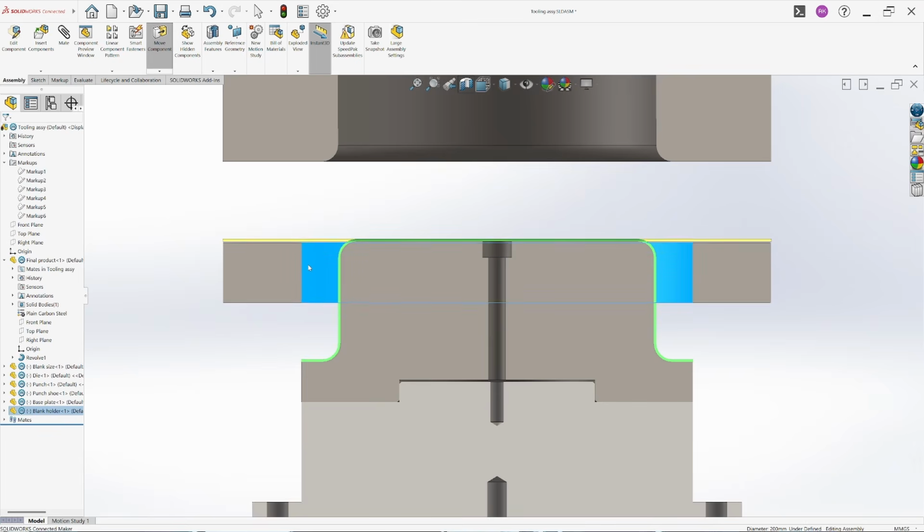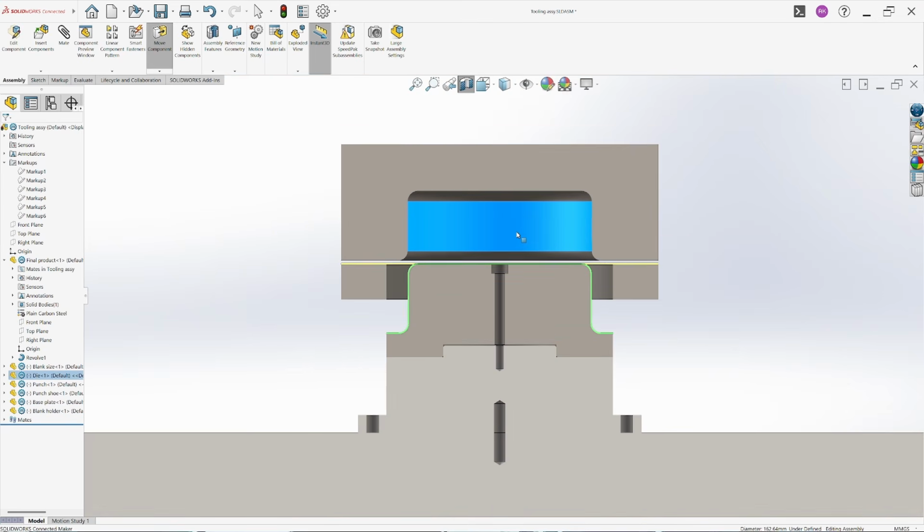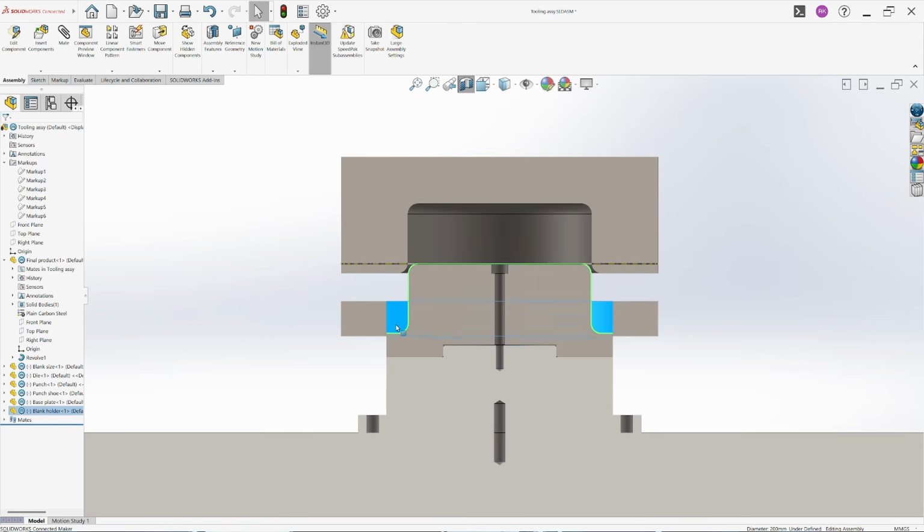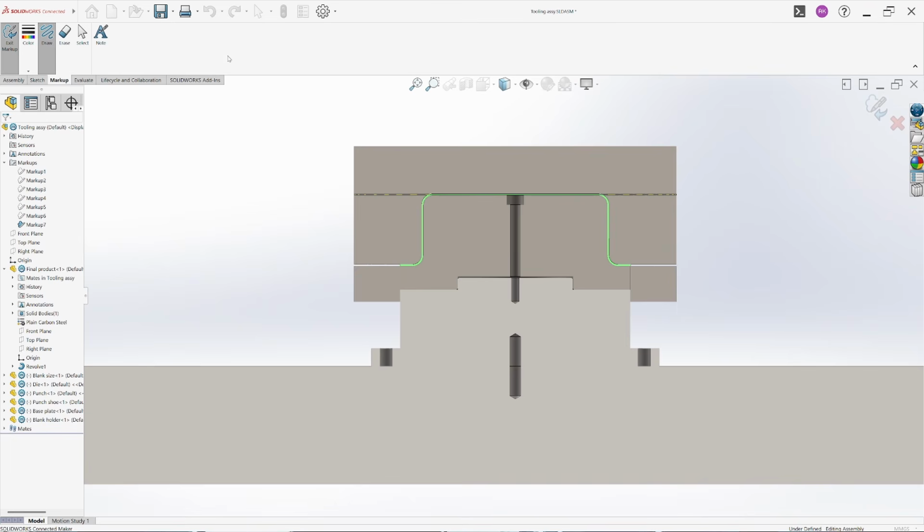So that will be our blank holder initially, and then our die will come down, and then it will start forming the sheet, and the die will go down as the sheet starts forming, something like this, and it will go up to this point. Now there is a problem. Now let's try to add our gas spring right here to support our blank holder, but as we can see there is not much space. Okay, so let's first try to bring our gas spring and then see what we can do here.